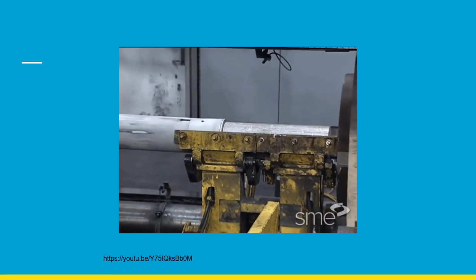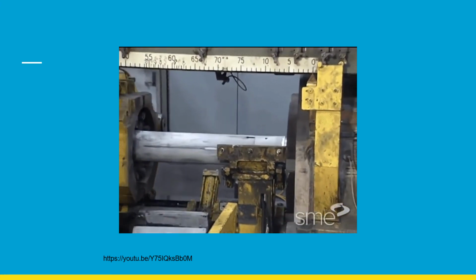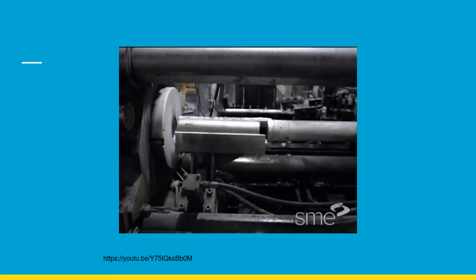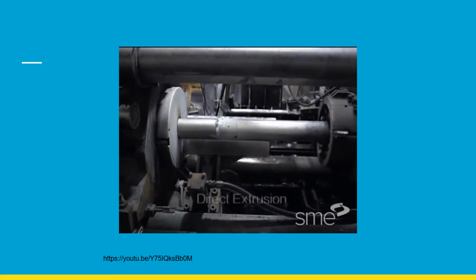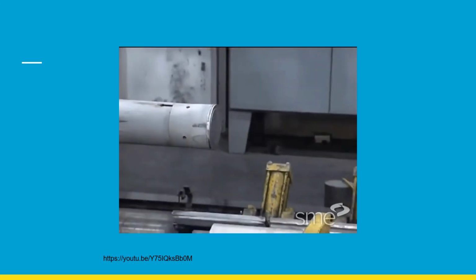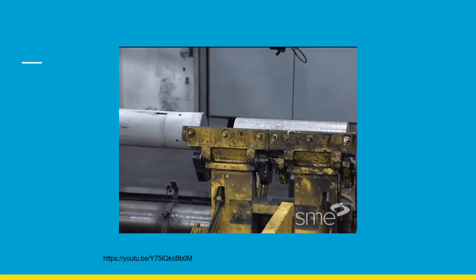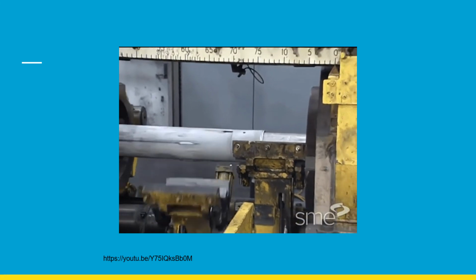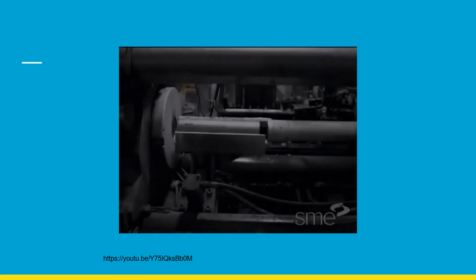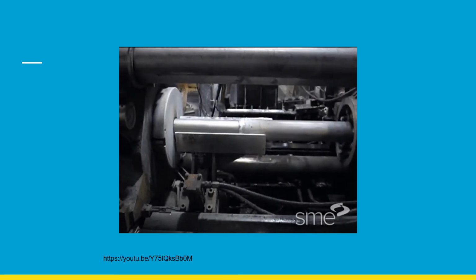The major disadvantage of this process is that the force required to extrude the billet is greater than that needed in indirect extrusion because of the frictional forces induced by the need for the billet to travel the entire length of the container. Because of this, the greatest force required is at the beginning of the process and slowly decreases as the billet is used up. However, at the end of the billet, the force greatly increases because the billet is thin and the material must flow radially to exit the die.